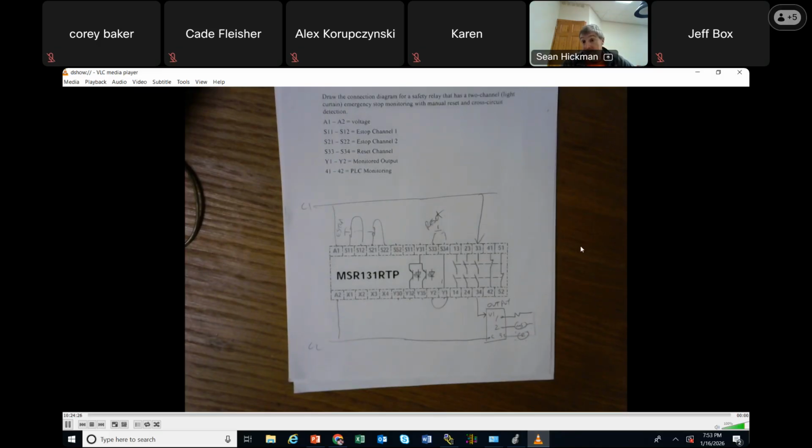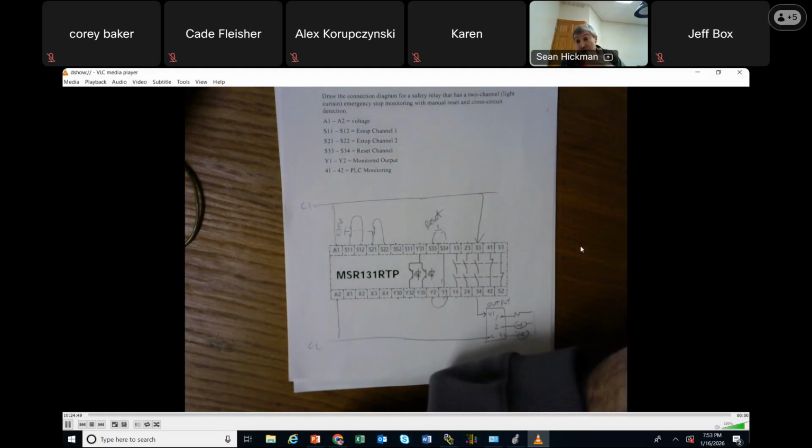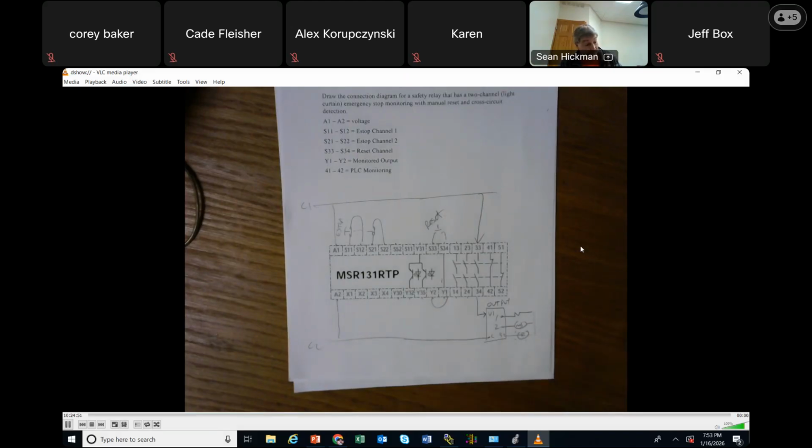Does that make sense, everybody? How you could bring down the output card completely. And then anything that's wired into it. We do that almost every motion output card. That's right. Yep. Bring down the output card. And then you bring down everything that's wired into the output card. So in order to get the output card to work, you have to just reset the safety relay. And then boom, instead of having a master control relay turn on the output card, have the safety relay turn on the output card, I guess, if you think about it that way.